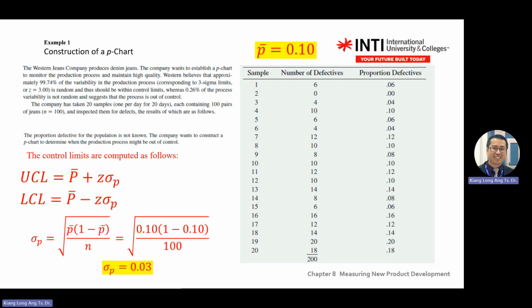If it's over the upper limit, what can you do? You need to alert the operator, or make an adjustment to the machine so that the trend can be moved down towards the mean. The main thing for your solution is you want to fix the upward or downward trend and move it to the mean.